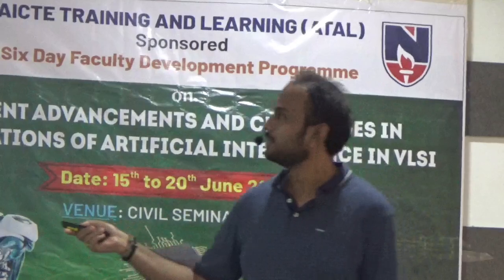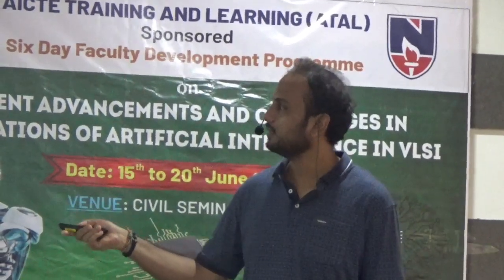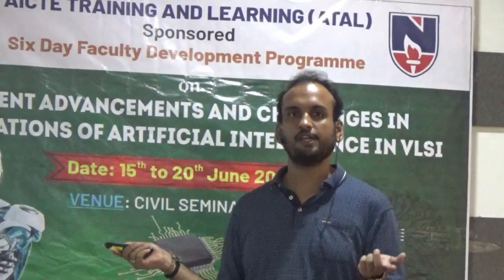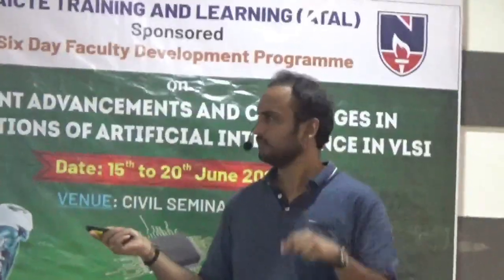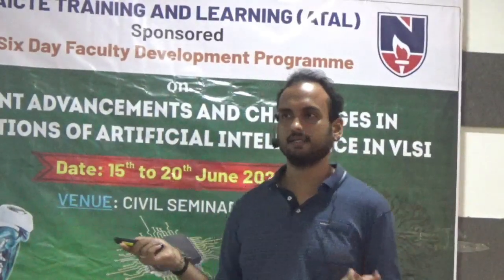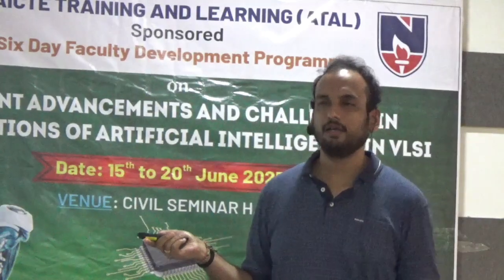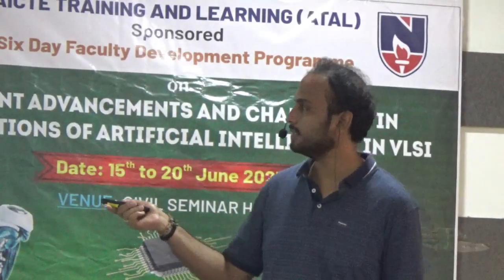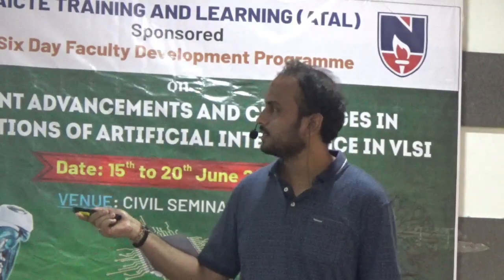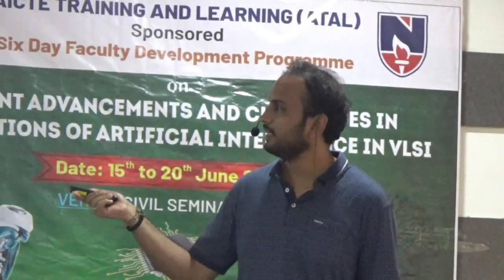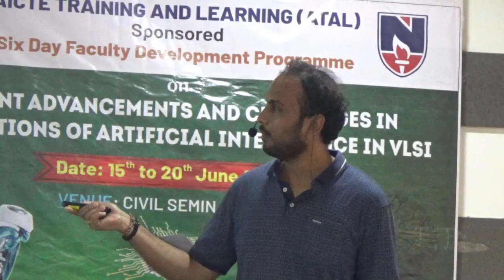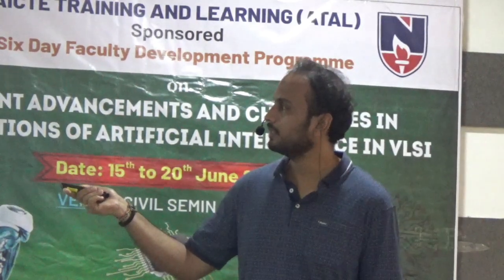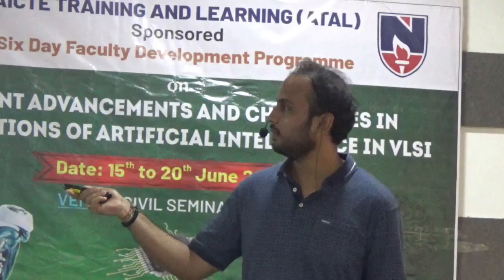So this is just to show the transconductance versus VGS. Earlier I showed you ID versus VGS. When you differentiate ID with respect to VGS, you will get the transconductance, gm. So if you differentiate this, you will get this characteristic. This shows how the channel length L decreases. The bottom one is the longer length device, and the top one is the shorter, narrower device.